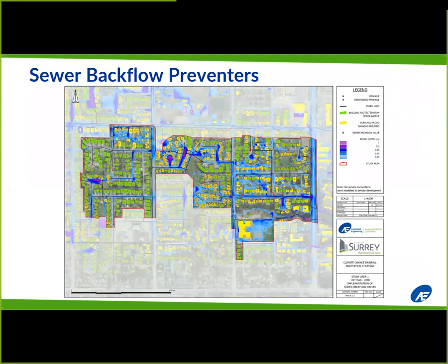And the second assumption was that these pipes do not have an existing backflow preventer on it, and that given that it's an older neighborhood and things have probably settled a little bit, there's a risk of flooding basements as a result of either cracked foundations or installation of other connections to these perimeter drains, whether it's for a sump pump or otherwise, that presents a potential intrusion point for surcharged stormwater to get into these basements.